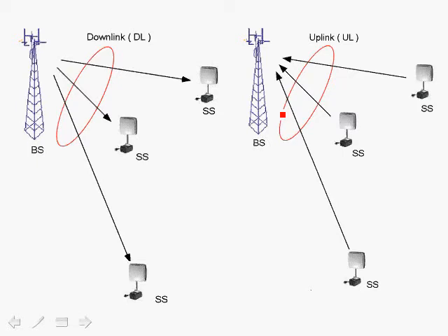So we've already discussed two important aspects. One is the fact that we have to have some kind of power control. There has to be communication between the base station and the subscribers, where the base station, through a number of transactions, adjusts the power level in the subscriber station such that nearby subscriber stations reduce their power, and subscriber stations that are further away increase their power, in such a manner as to achieve power management and reduce the amount of interference and overload.